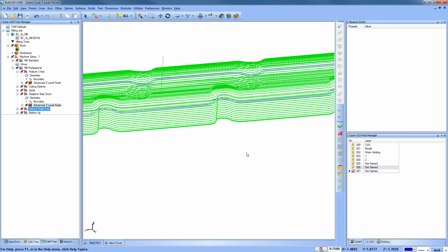And then with an advanced posting tab with your post processor, you could actually put cutter comp in it. You could have it lead in, call cutter comp, and it could do that for every level. But it's not an in-the-box solution. It's something that you'd have to pick up. Okay? Does that make sense? Yeah.